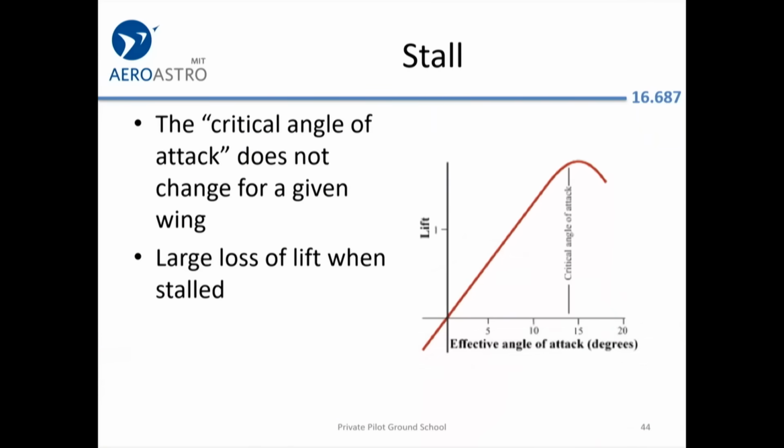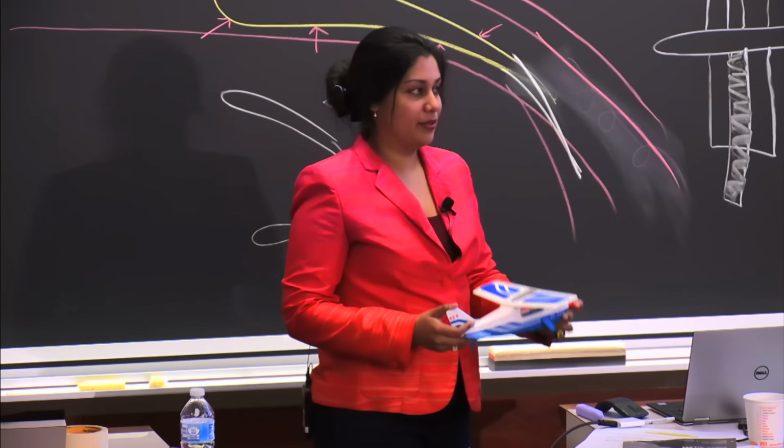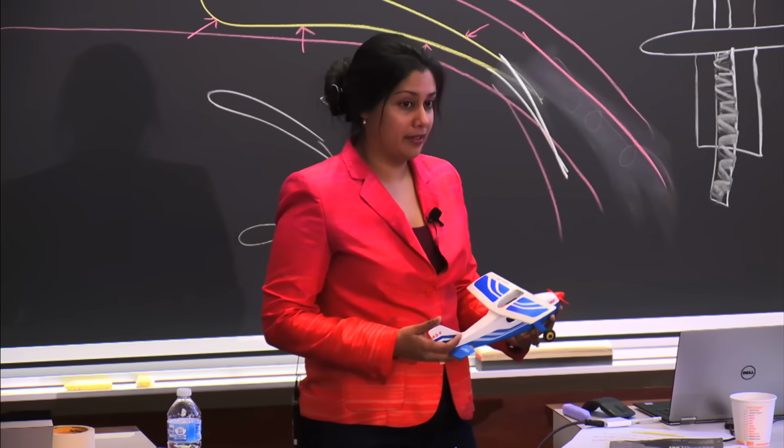And again, once you have that angle of attack too steep, then there's a very significant loss of lift, which is not good when you're flying an airplane. So when can you stall? At any airspeed and any power setting, and it's really based on the angle of attack.